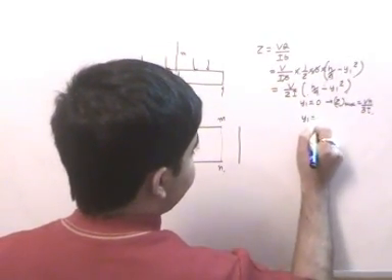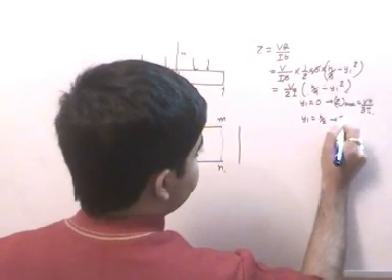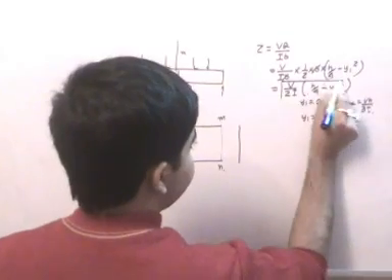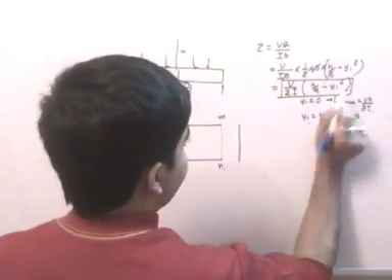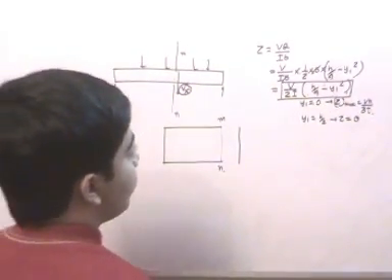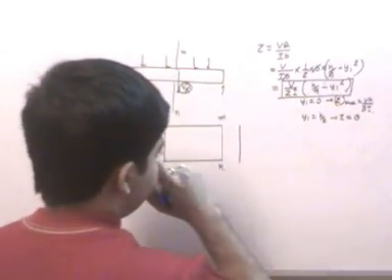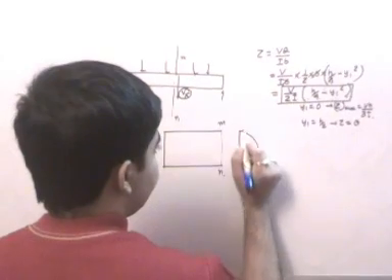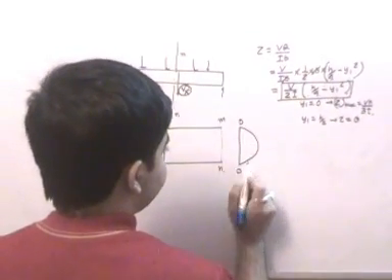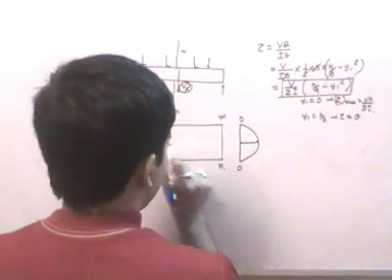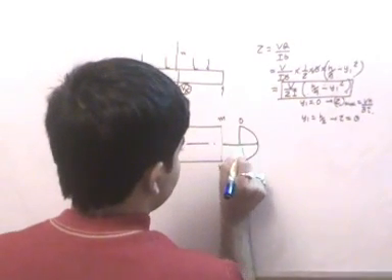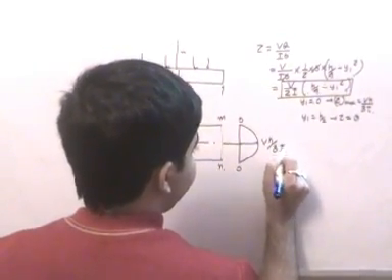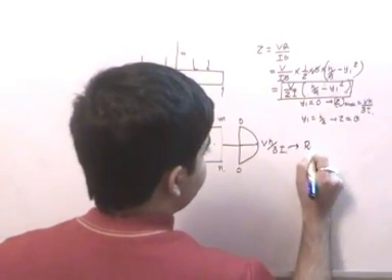When y1 is equal to h by 2, you have tau equal to 0. And from here we see that the shear stress across a cross section is some kind of a parabolic function because of y1 squared. So essentially it will be a parabola like this, wherein at the ends we have zero shear stresses, and at the middle or the neutral axis we have the maximum value of shear stress, and that will be given by Vh by 8I for a rectangular cross section.